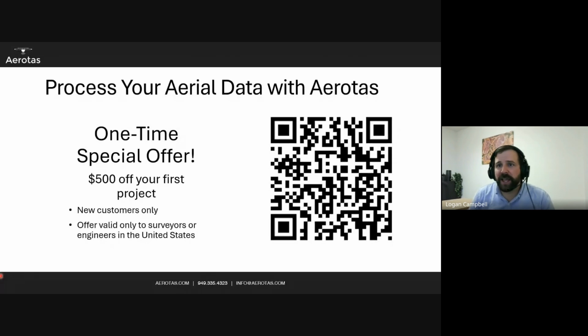Is there a benefit to flying a double grid mission compared with a single with more overlap? I would recommend you look in our library of webinars. Some of them are on YouTube, one about flight operations. Short answer is there are very few circumstances where a double grid mission will actually improve the data. There are a few edge cases, but I'd say in about 98% of land surveying focused missions, a single lawnmower flight pattern is going to be better, not just good enough, but better than a double grid mission because there's a lot less data with it as well.